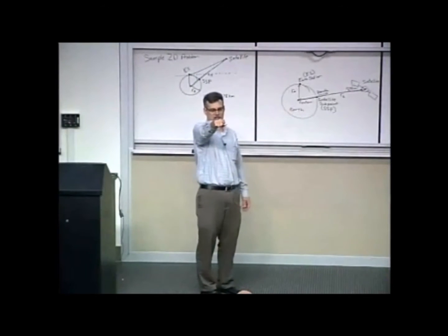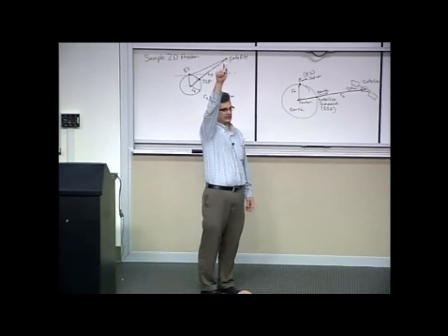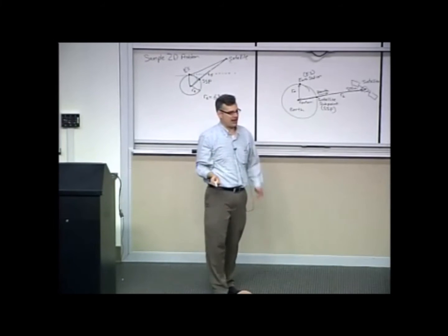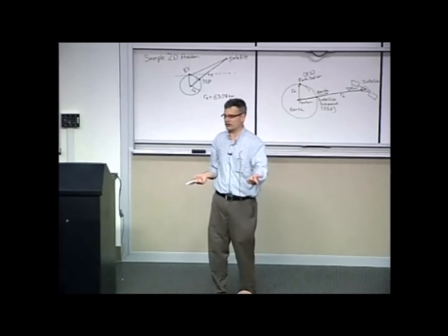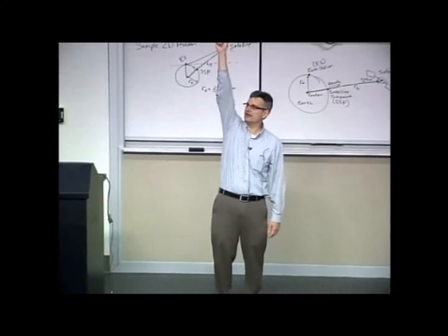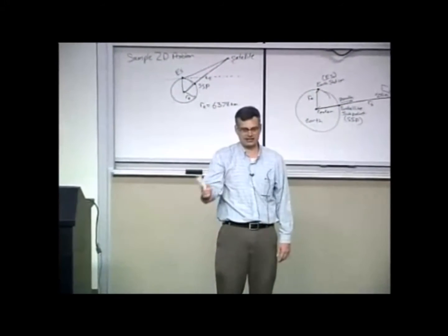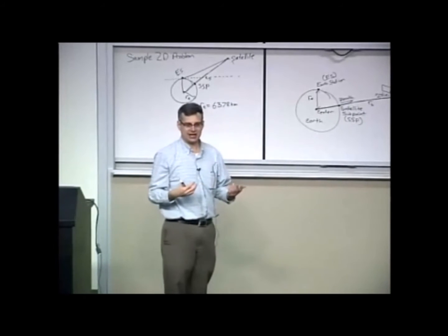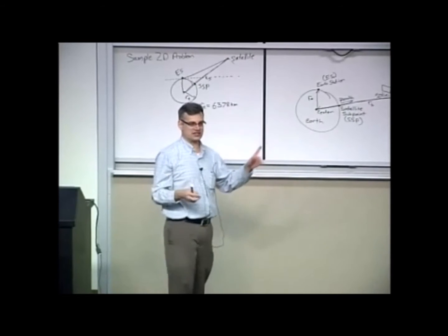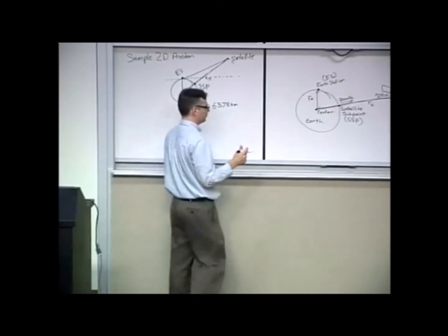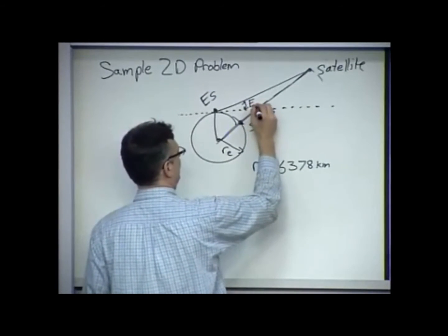We're going to measure elevation in this class as a function of degrees away from that horizon line. Now, keep in mind, that's different than how the mathematicians taught you to measure elevation, and the electrical engineers that taught your EMAG class. They're teaching you elevation from the z-axis. This is 0 degrees, and then you go down this way to 90 and 180, etc. So just recognize that a lot of the formulas that you'll see for elevation in your math textbooks, you've got to massage them a little bit to make it into a look angle. Okay, so this is the angle that we're after. E, we'll call it E little l, L.